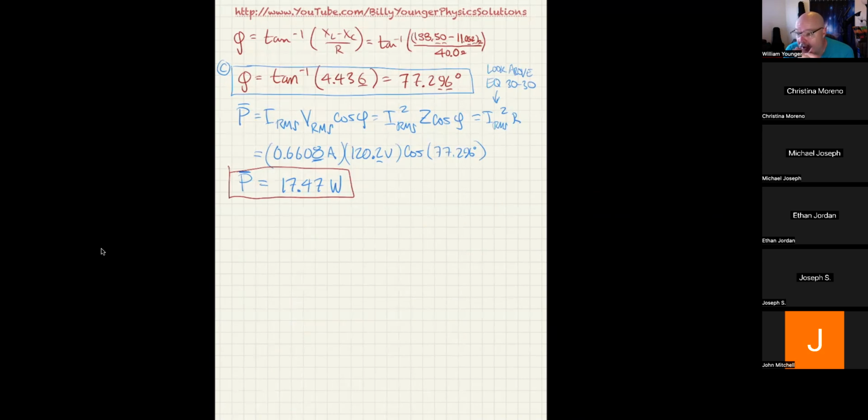And then another one, V2 equals V0 times, notice it's the same peak, cosine of omega t plus 120 degrees. And then the third one is V3 equals V0 times cosine omega t plus 240. So that's what the triphasic voltage is.